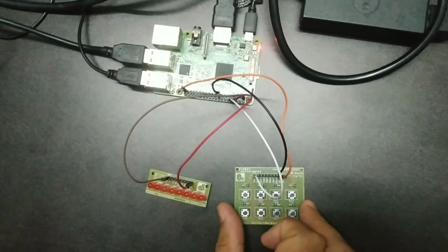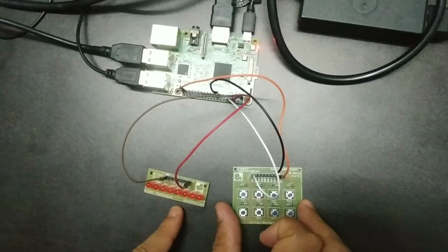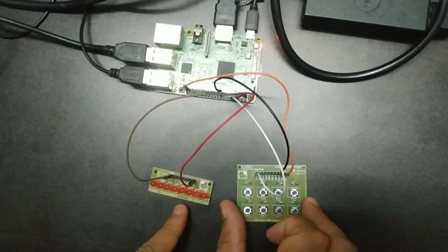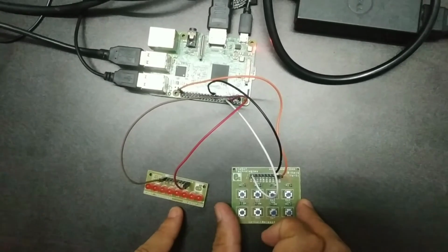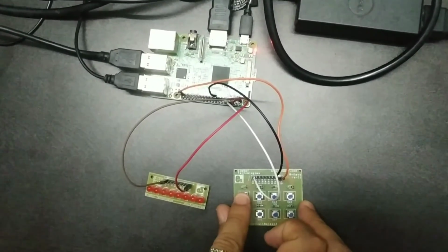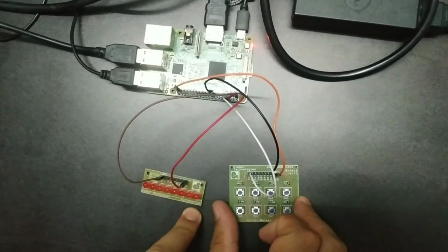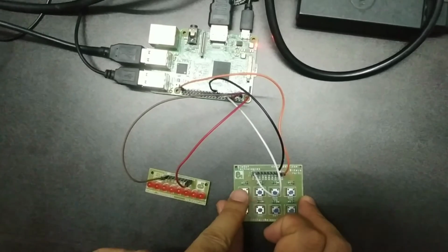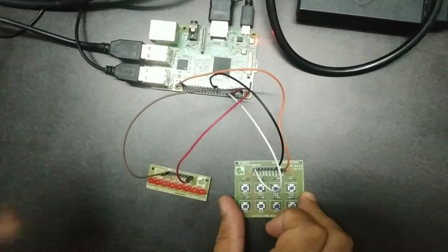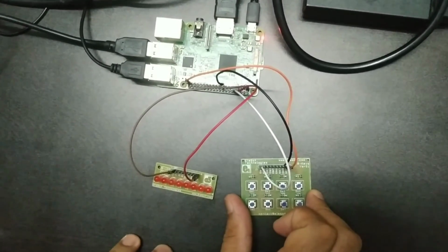That is, the LED will blink continuously with, let us say, the time interval of 1 second in between the high and low, and it's going to be a continuous blinking operation that will take place if the push button is not pressed. If I press the push button, then the LED will remain in the high state, right? That means it will remain in the on state till the time the push button is pressed. When I release it, it will come back and again start blinking, right? So this is what is going to happen in this particular circuitry.